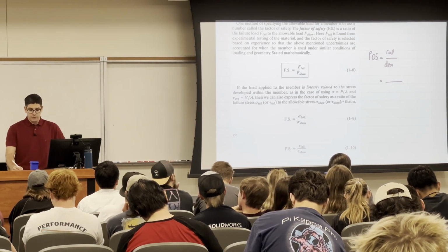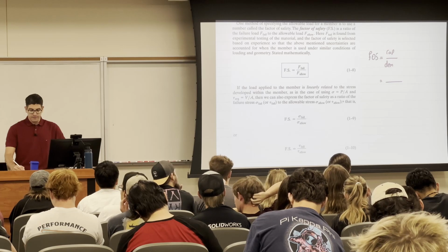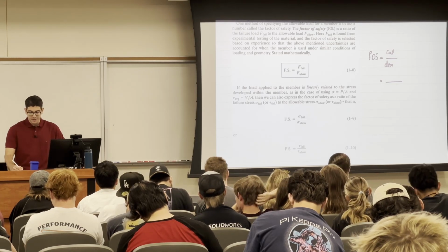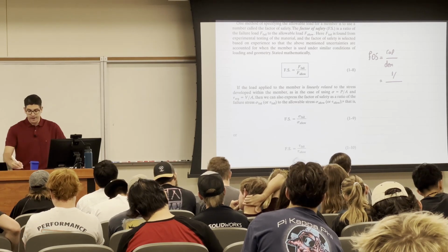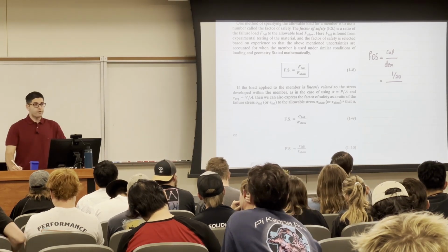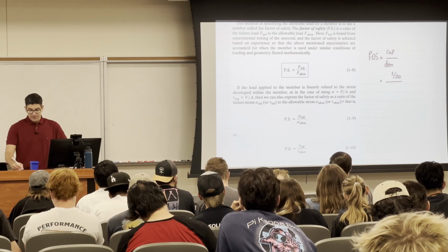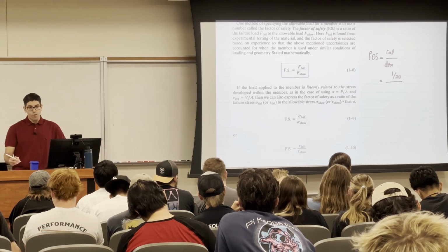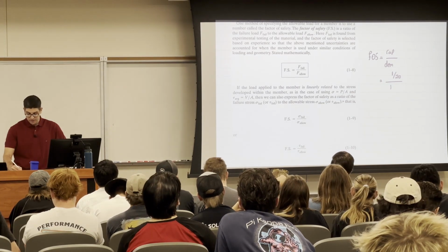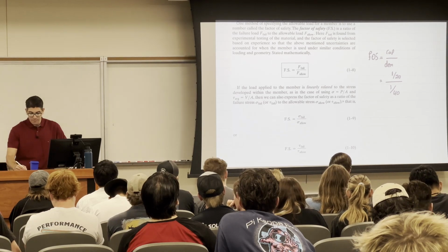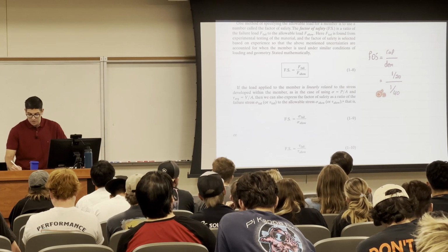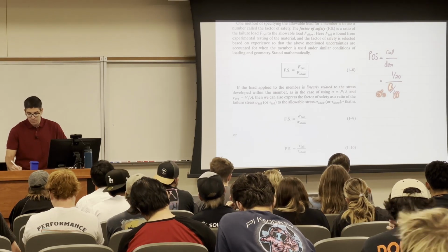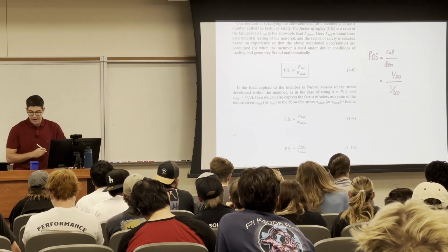So, for example, I want to have a factor of safety of 2. The capacity is 1 over area, as this one is a stress over area, and I'm using an area of 20. And this is my capacity. But I want to use 40. So this is demand. I'm saying 1 over because this is the equation for the stress: stress is equal to force over area. And I'm just saying force is equal to 1 because they're going to cancel each other anyway.